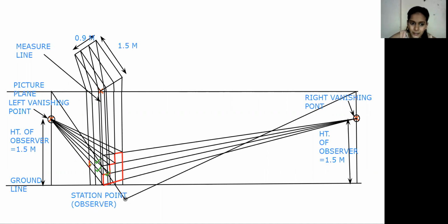So we have this point, and consider these 2 vertical lines of the first and second top portion of the plan. Okay, so between the two vertical lines and between these two inclined lines, our tread will come. So join our tread first, like this tread. Again, on this vertical line, our another riser will come.